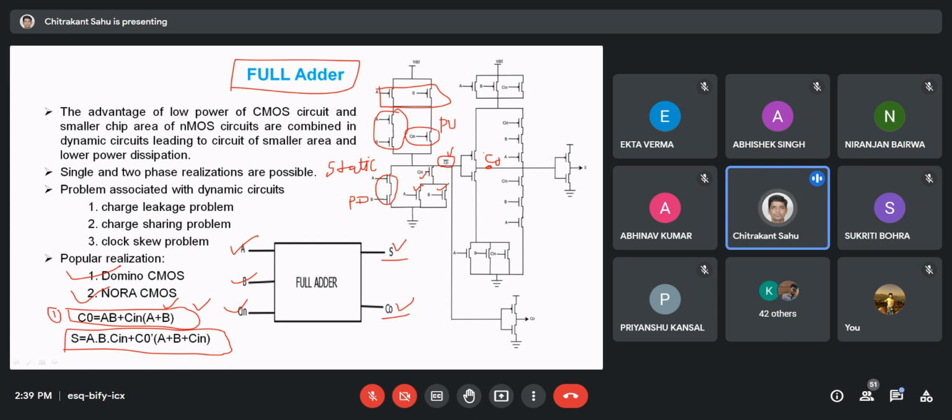Okay. So why has it been done this way? Because in this equation you can see that the sum will have this particular term, which will be used in the calculations. If you write the detailed form of the sum, it will make a complicated circuit. If you do the minimization first, that is the rule of minimization, if you do the minimization of the Boolean expression, then the resulting circuit from the minimized structure will be minimum, right?